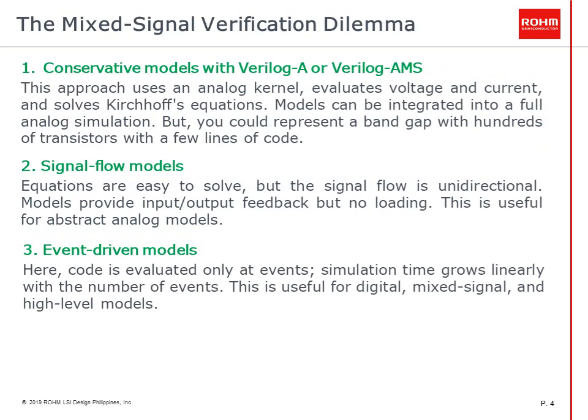Conservative models with Verilog-A or Verilog-AMS. This approach uses an analog kernel, evaluates voltage and current, and solves Kirchhoff's equations. Models can be integrated into a full analog simulation. But, you could represent a band gap with hundreds of transistors with a few lines of code.